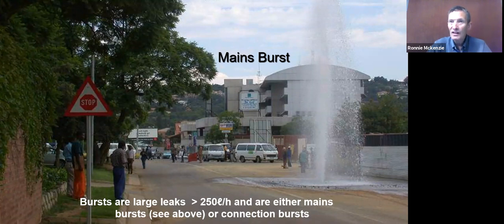This is running at about 20 cubic meters per hour. A typical mains leak will run at anything possibly from about a cubic meter per hour, on average, up to 10 or 20, but it can go as high. We've had mains bursts up to 1,000. So it depends how big your pipes are.